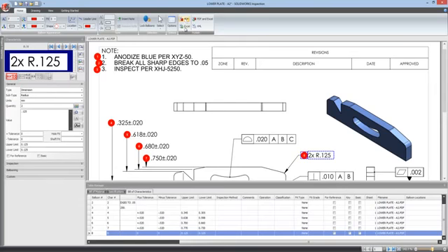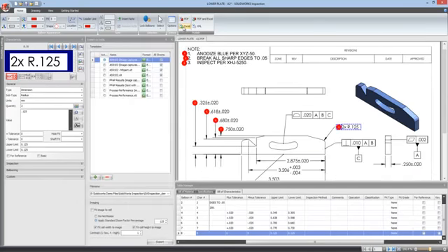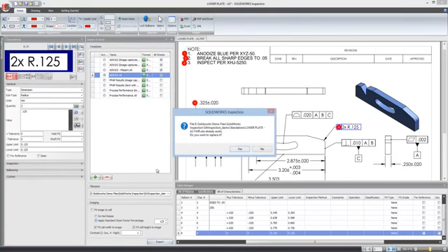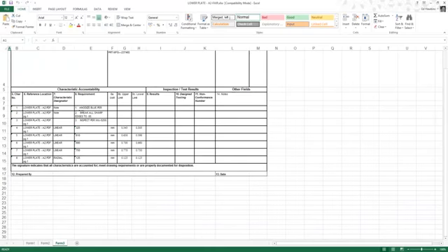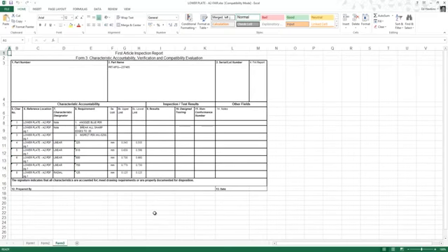So once we've done that, the next stage would be to produce an Excel report, which we can do again based on a template here. So if we just pick a template and we'll export that, so we can take a look and see what it does. So if we just open Excel, you'll see it generates us a really nice sort of check sheet for us to start to fill in dimensional values or log those or give the sheet to somebody else to fill in. If you are filling it in within Excel and we fill in some values, you'll see that values that fall outside the range that we're allowing will go red. If they fall within, they'll go green. So we'll get graphical feedback for those dimensions on screen. So as I say, this is a very brief overview, but that is the standalone application.